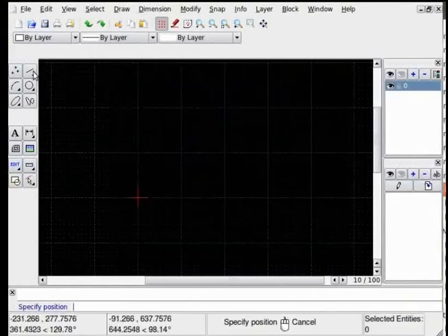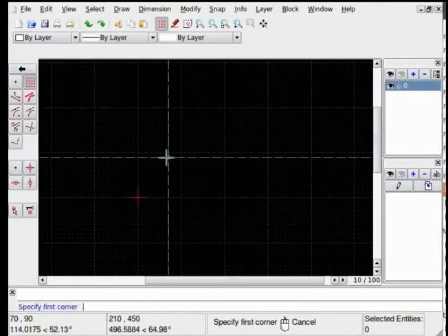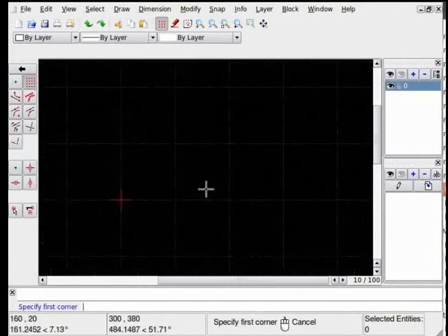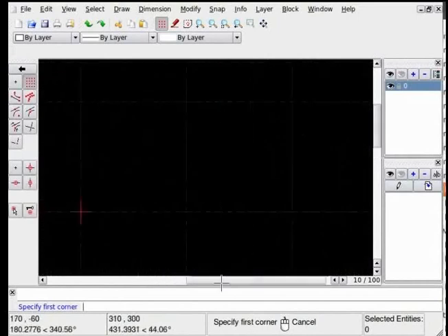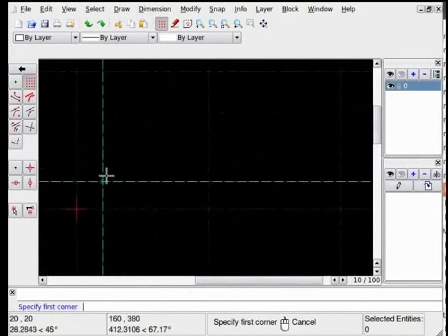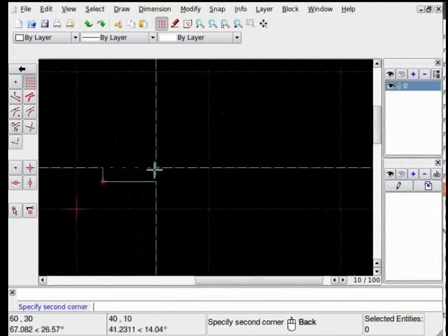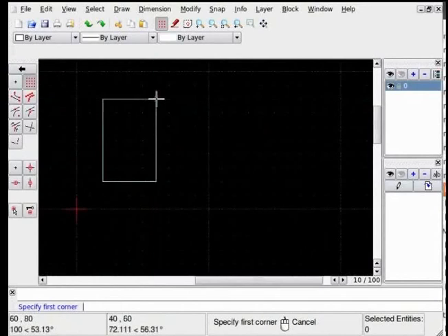From the toolbar, select the Line tool and click on the rectangle icon. Choose the Snap to Grid option. Zoom in on your drawing area by using the middle mouse button if your grid size is too small. I'll create a rectangle of 4 grid sizes by 6. So left click for the first corner, and again left click to complete it.